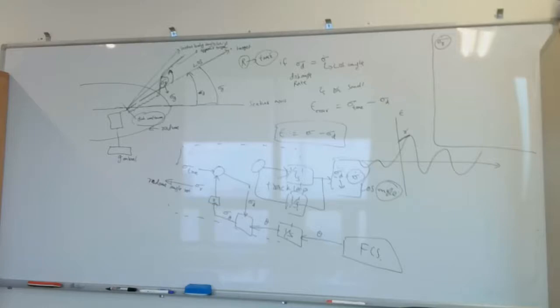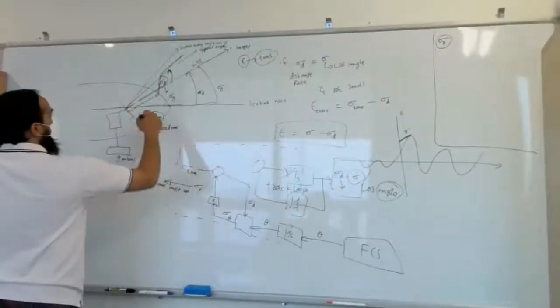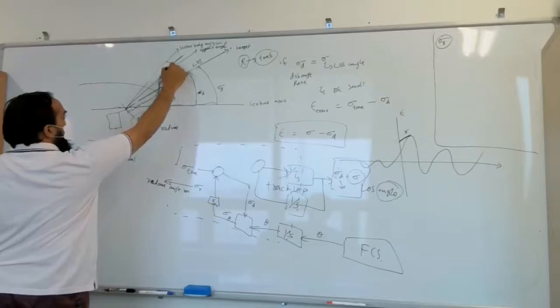But with the random effect, there are many things, because the angle of the radar depends on the gimbal. So this is also included in this block diagram, so that we have this angle, and then the pitch angle. Pitch angles come from the FCS, the aerodynamics. The pitch angle is this one: the seeker body axis to the line of sight.